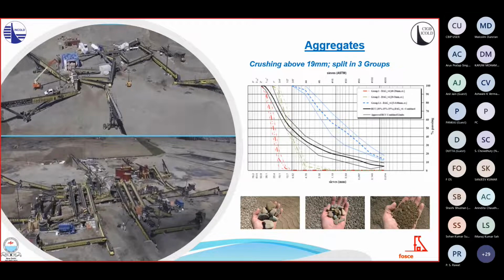Alluvium deposits with natural rounded particles and some plasticity in the fines with a relatively high natural silt content. The initial mix design efforts with such materials were not very promising, and first mixes exhibit a relatively high water demand to achieve the desired consistency, without avoiding a significant problem of segregation in the mix.